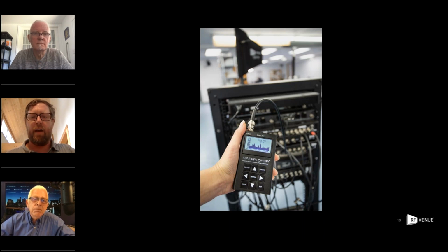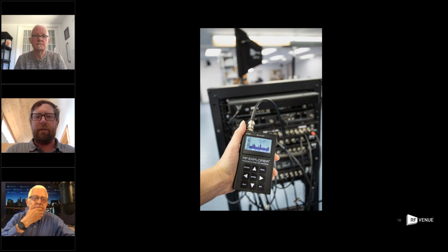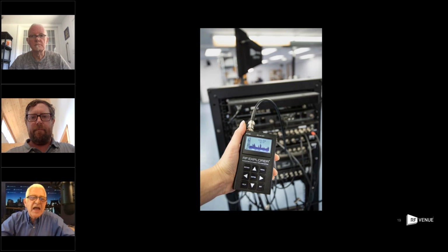If you have a bunch of IEMs that are transmitting at 30, 20 dB, 20 mil, whatever it is, it's low power enough, in terms of path loss and everything, to the input antenna on the RF Explorer that you're not likely to fry your unit walking around IEMs. It's really more when you're getting into much higher powered stuff. Or you're measuring it to actually measure the output of a transmitter. Or you're actually piping in the transmit signal, correct, Pete?